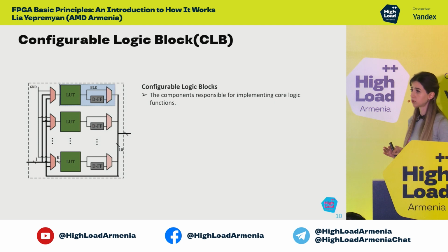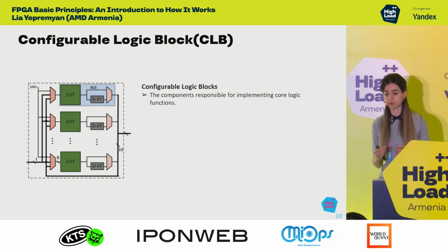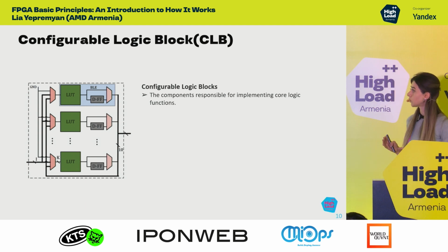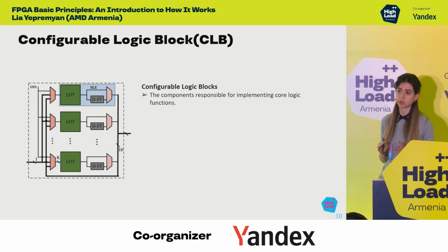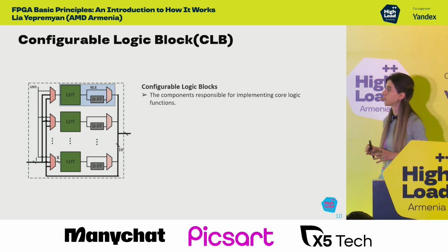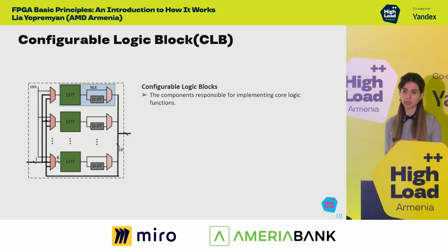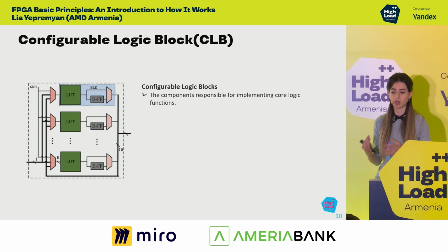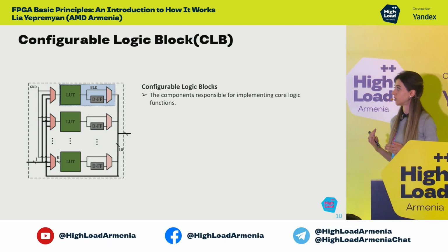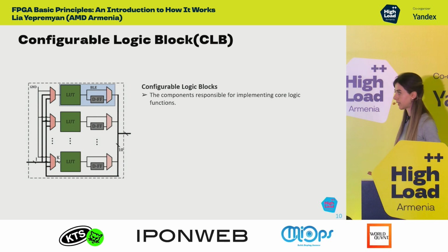Configurable logic blocks, as I said, can do many different modules and functions. The main block is the lookup table, which is responsible for logic. The lookup table stores the combinations of inputs and reproduces them at its output. So they can be configured in terms of our design.